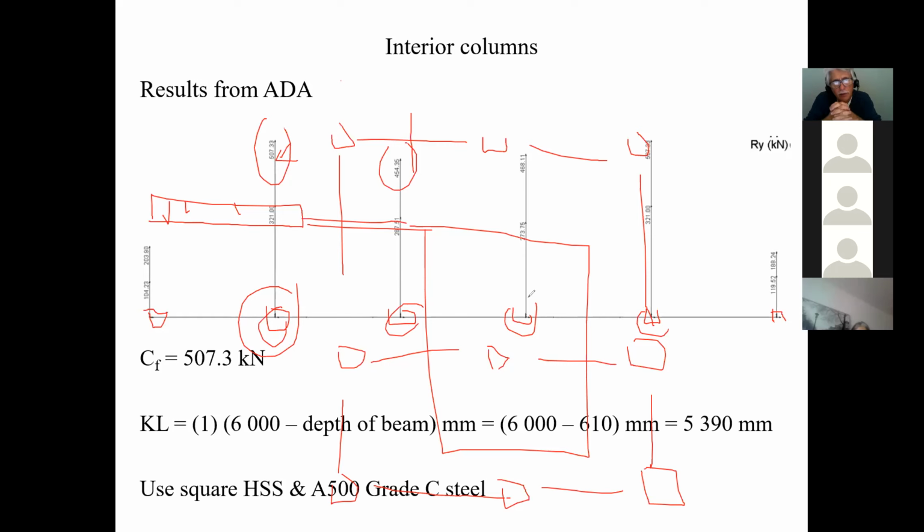But here, when it comes to columns, guys, the other thing about steel is that you have to keep in mind there might be a little bit of savings when you specify, but because you're not repeating it over and over again, that saving might not be there. Because in steel, what is really economical is if you can repeat. You understand? When the guy buys his HSSs, he buys them all one size. Because if he buys his HSS for this size here, and all of a sudden he has to scrap 10% of it, what savings do you have?